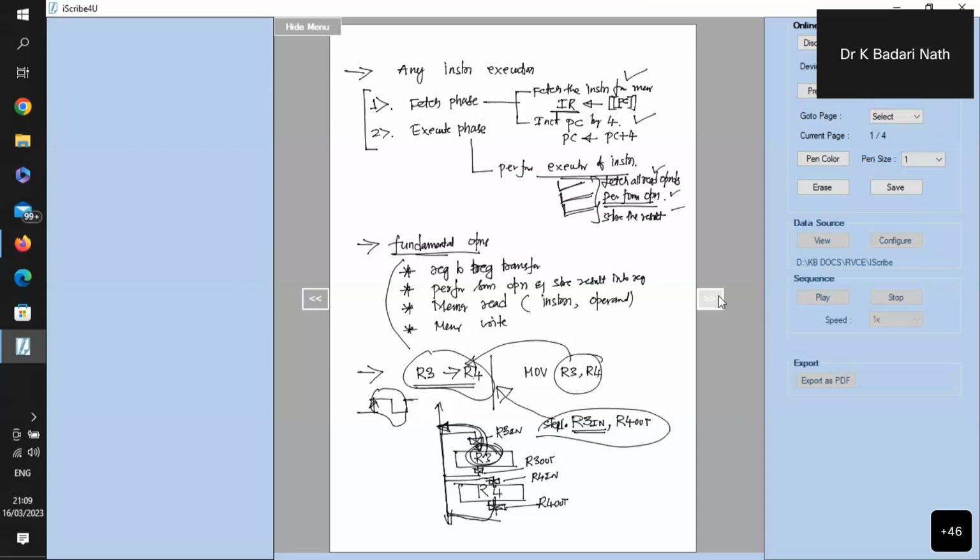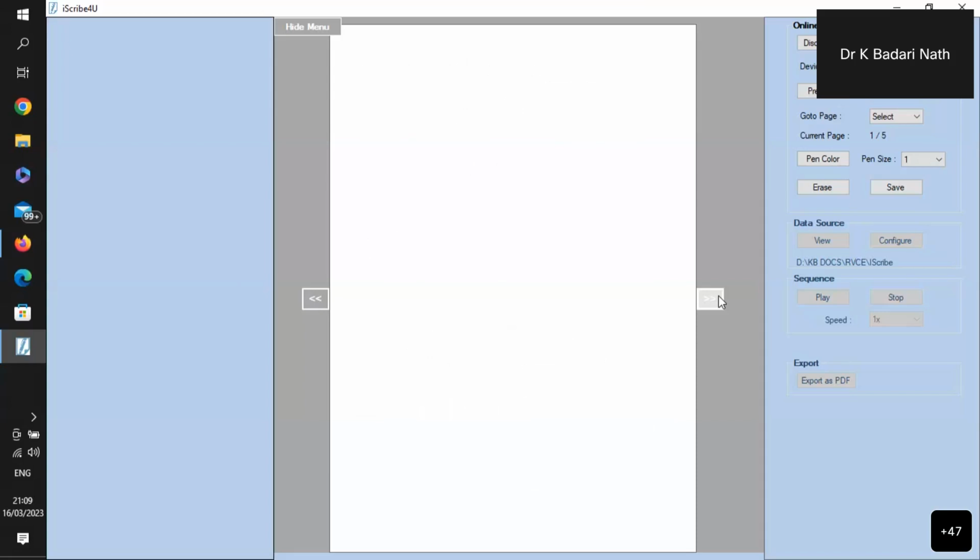So like this, we have to identify what small tasks we can complete in one clock cycle. When I say task, it is nothing but what control signal you're supposed to generate, which in turn activates some operation. The sequence of control signals I'm supposed to generate are R3 out and R4 in. So like this, I can finish the basic operations. Now, in another 5 to 10 minutes, I'll conclude. So now I'll go to another operation which I want to perform.